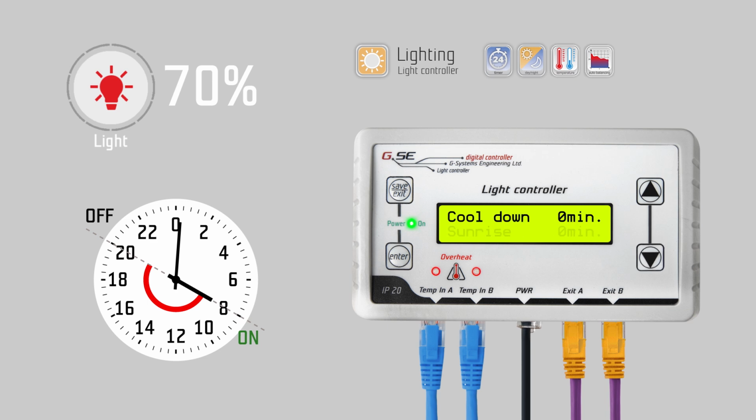The time for the sunrise, for example 5 minutes, will start with the on time, and dim the light from the minimum dimming value to the maximum dimming value during this set time. The sunset, for example 3 minutes, will start according to the set time, before the off-ending time, and reduce the value from the maximum to the minimum value you have set.